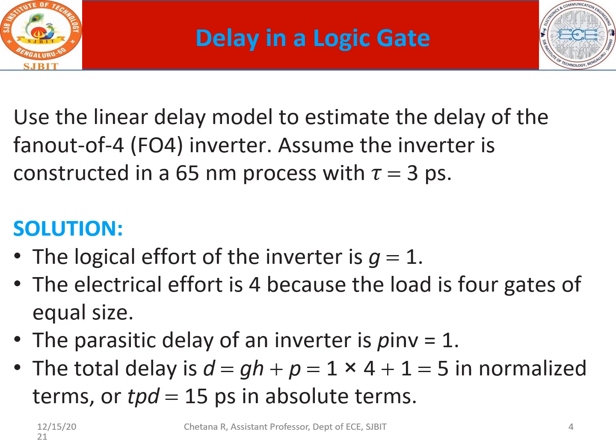Now, what exactly we are supposed to do here before calculating the delay is find out the electrical effort. So what is the electrical effort? As I have already told you, H, as per the author, is also called the electrical effort. So what is H? H is nothing but the fan out. How many devices is it driving? 4.